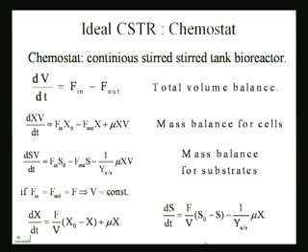And the last thing would be the substrate balance equation, dS/dt equals F over V times (S naught minus S) minus 1 over Y mu x, right.